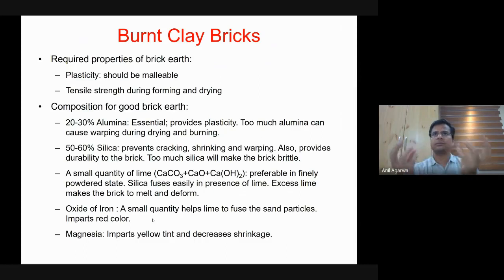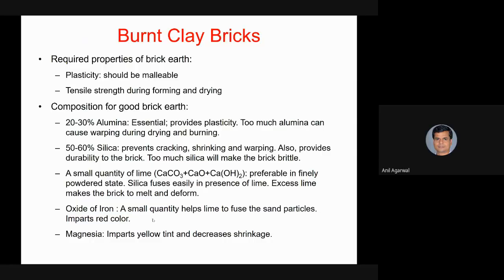You want the flexibility without having to add too much water, because if you add too much water, you actually lose strength. Ideally, it should have more malleability and plasticity when it is wet, but after it dries and becomes hard after burning, then it should have high strength.